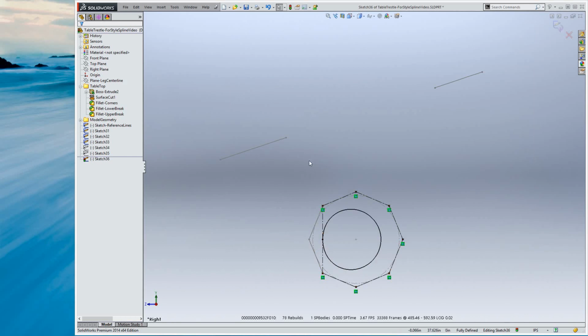Most of the time, though, if we're going to create something like a style spline, we might be working with existing geometry and trying to create a curvature continuous path between them. So we can come up with the first one, make that tangent. We have to make at least, I think it's a 5th degree to do curvature continuous on both sides. 1, 2, 3, 4, 5, 6, 7. So this one's 7. That'll give us 2 additional control points in the middle to control the shape.